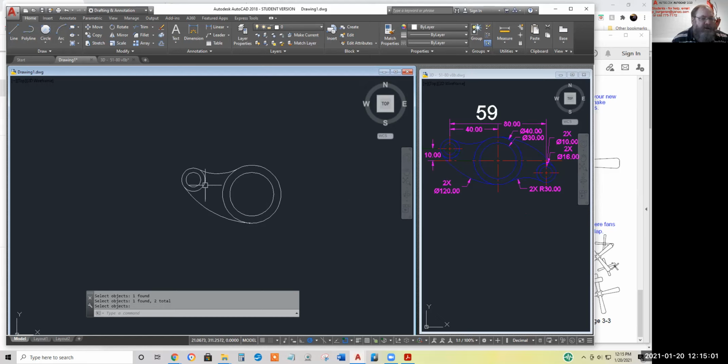I think I can mirror it straight across and then mirror it on top of itself just as well. We'll go to mirror, select the two arcs and the two circles and hit enter. We'll mirror it to form a boomerang and hit enter. No, I do not want to delete. Now we'll go to mirror again and select the mirror copy and draw a horizontal line through quadrants or midpoint, the middle of the circle, and hit enter. Now check it out.